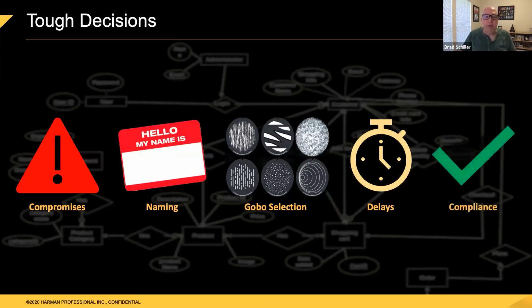And then finally, the other tough decisions come around compliance. Most products have to go through some sort of compliance, so you've got to designate hopefully a first article or a beta unit to send off to an independent lab for testing. So there's testing for UL listing, EU, FCC, CSA, which is Canadian, many different types of compliance that often needs to happen.